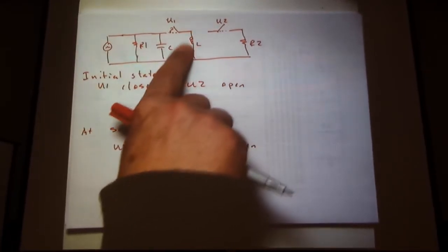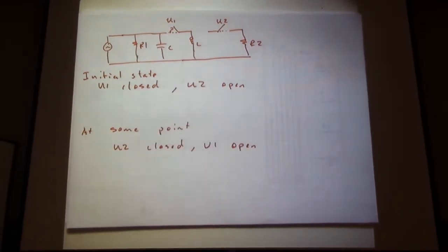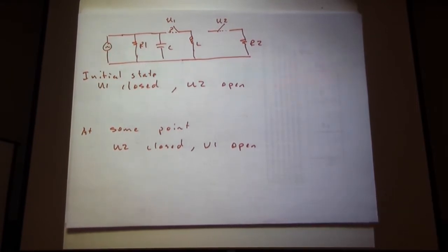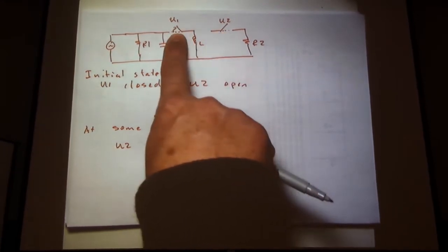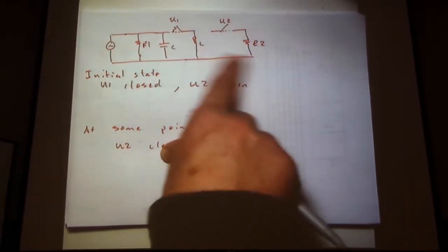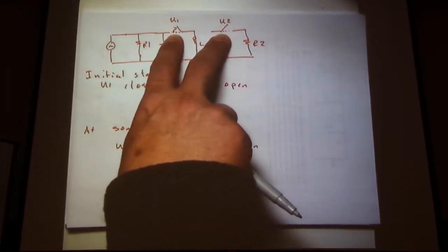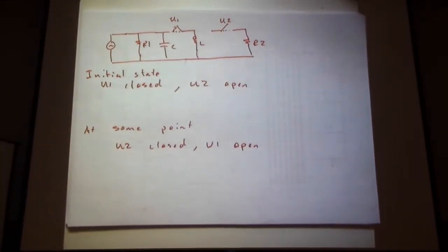Once you open it, in that type of situation, you have a catastrophic failure here, but hopefully it prevents catastrophic failure somewhere else. Burning out a good inductor is better than burning out a substation, or a housing development or whatever. There are better failure modes in this, but that's an overview. So what do you have to do? Well, you close this first, then you open that. That gives a path for the current to flow, because you can't do two things simultaneously. So close this one first, then open that one.